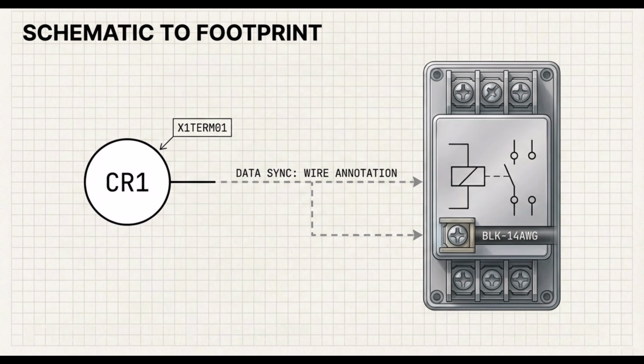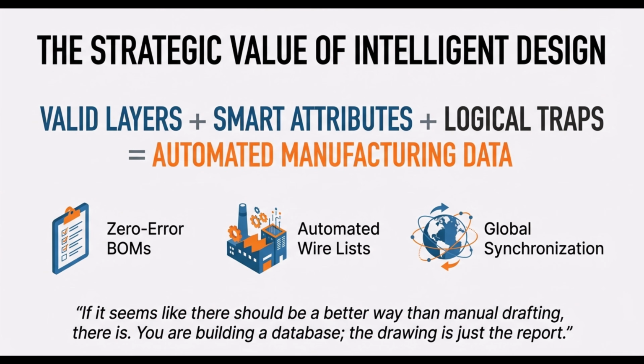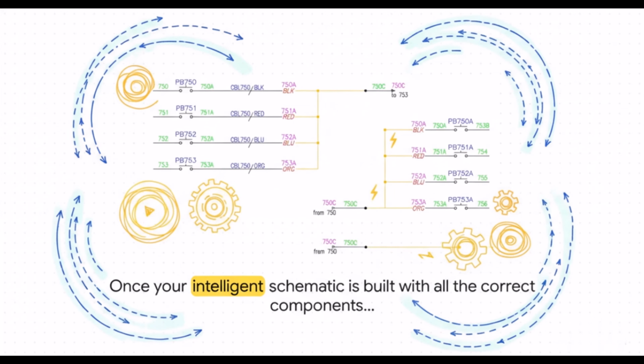But the source warned that this isn't foolproof. If you didn't use the right footprint symbols, this all fails. Yes. It relies entirely on the footprint lookup database. If your schematic symbol doesn't map to a physical part number that has a defined footprint, the automation just hits a wall. It might give you a generic box or nothing at all. It all comes back to the database.